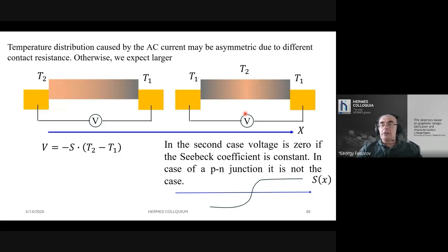You can say that the heated region of the channel behaves such that main carriers escape from it. And then if this side is p-doped, holes will escape rightward, and if this side is n-doped, main carriers, electrons, will escape leftward. So there is some similarity to photodetectors based on semiconductors, but it's very primitive.